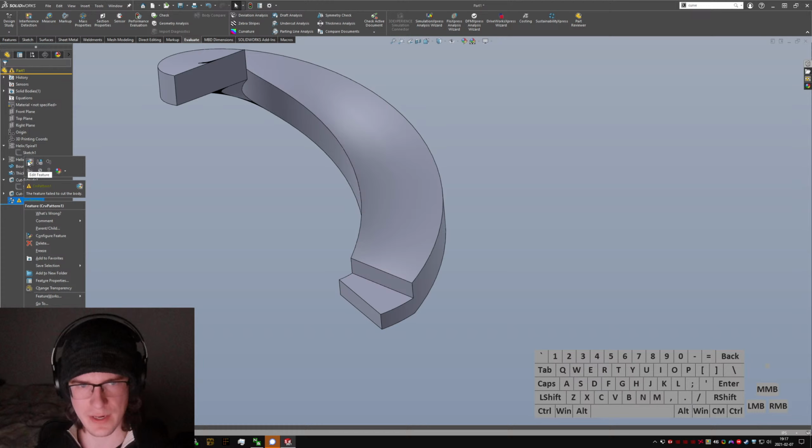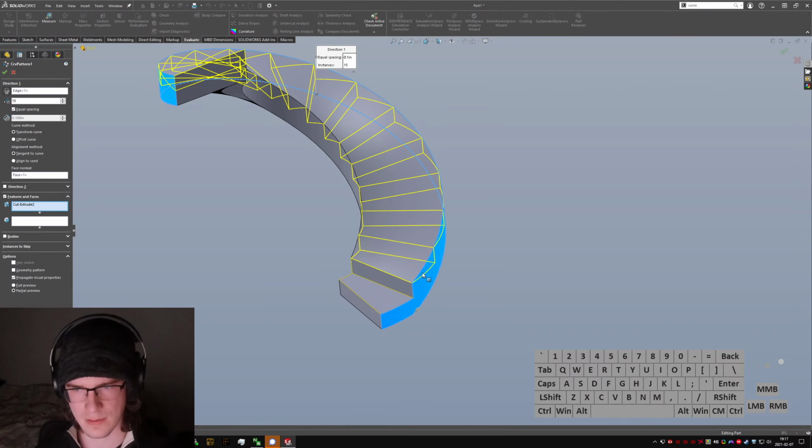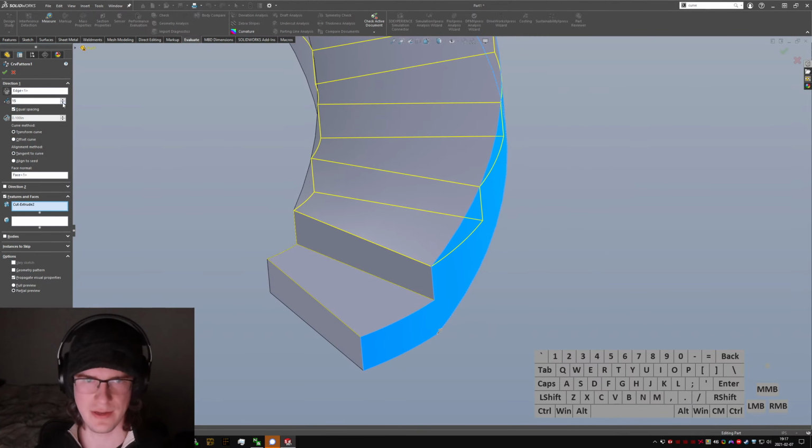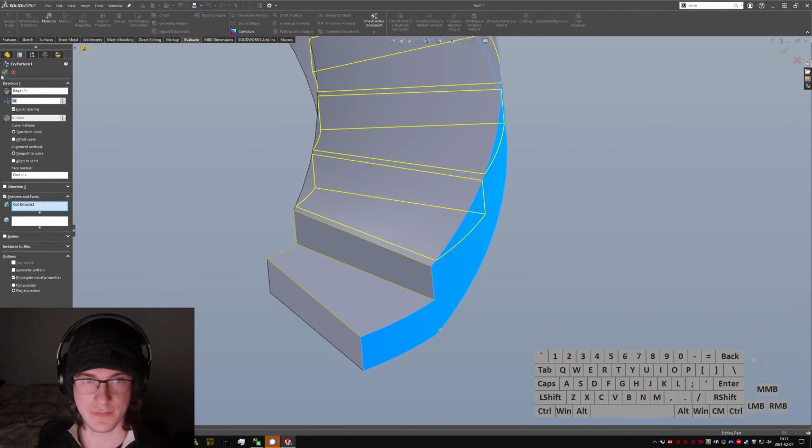Why does this one break? Feature failed to cut the body. But why? Why would you do that? Does it work with 14? Works with 14. Makes all sorts of screwy faces, but it works with 14. I bet it'll work with 16 too. That would be bothersome. Failed due to geometric condition.